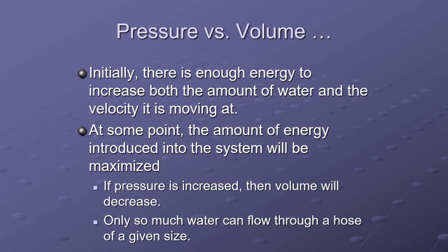That's why portable pumps like Mark IIIs are really good examples of it, because they're the one pump that we all run at max RPM because that's what it likes to run at. When I'm looking at a $200,000 fire engine, it makes me a little nervous to crank that thing up as high as it'll go. I'm not always at max RPM. Just a couple different ways to look at that. So this really comes back to the performance curve on your fire engine pump.